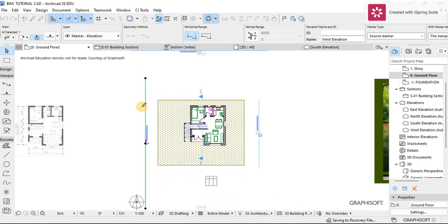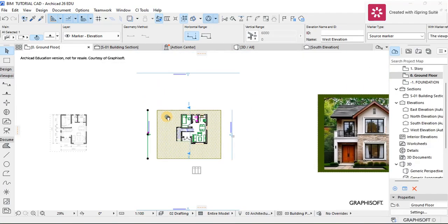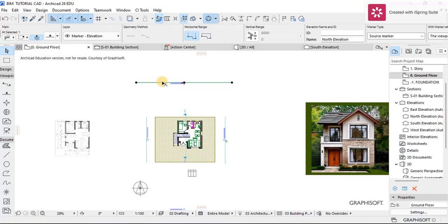So you see here, click the node, then the last option, and then minimize it up to the site edges. Yeah, then I'm going to do the same for this one and drag it back to somewhere here, and then minimize it up to the site edges.